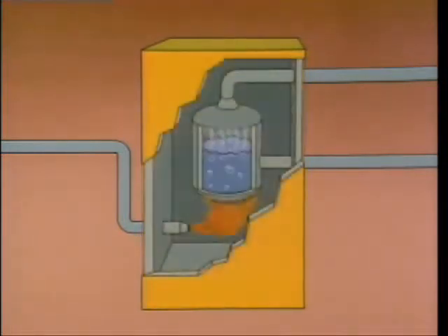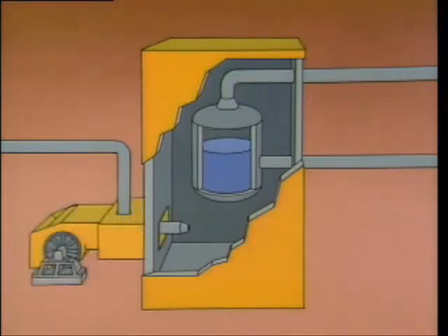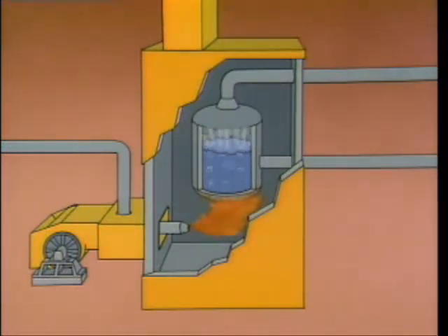This boiler can be modified further to make it more efficient. By adding an insulated casing, we can minimize the heat loss, but this creates another problem. The flame goes out because the casing cuts off the source of air. To correct this, we'll add a fan to supply air to the boiler and an outlet to remove combustion gases. Although this design is still greatly simplified, now we at least have a boiler that provides a constant supply of steam efficiently.